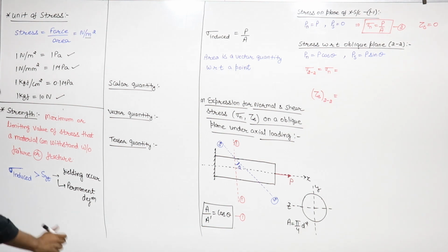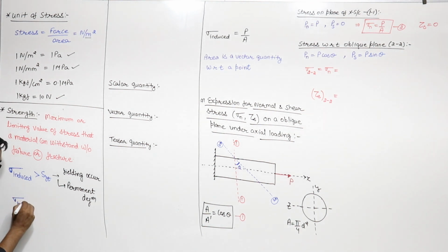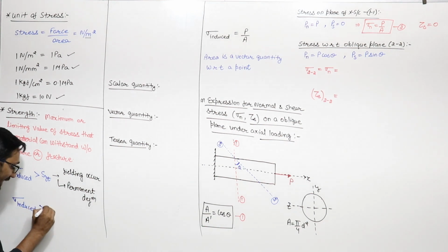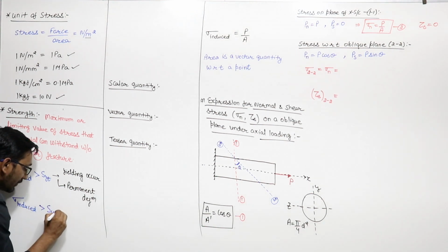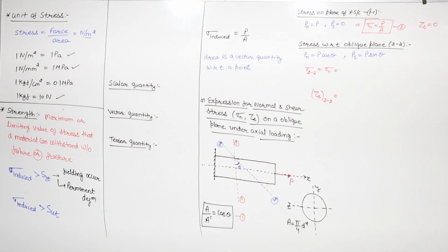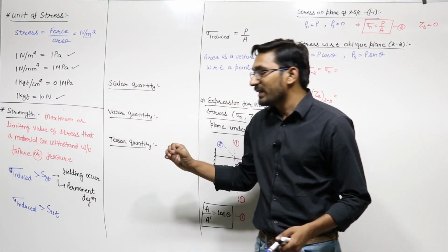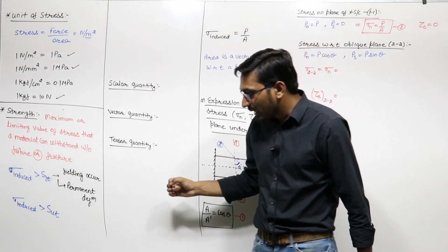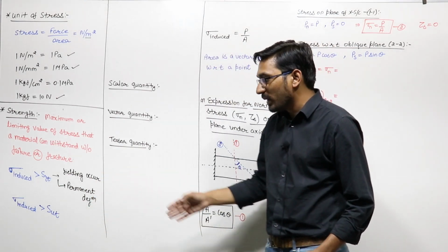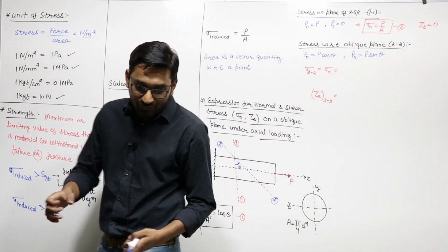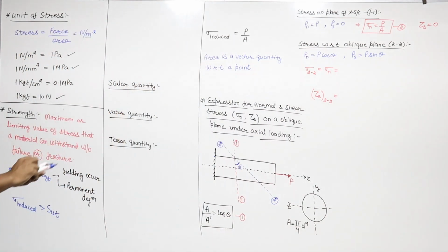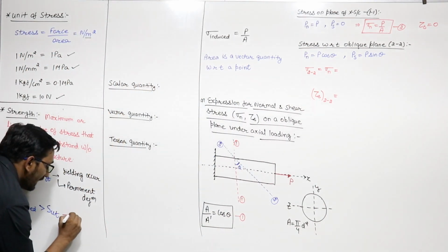And if the induced stress is greater than SUT, SUT is your ultimate strength during tension, then we can say that your body will fracture.